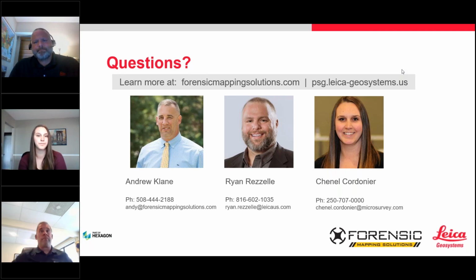Okay, great. We have a question here about the ground sampling distance. Andy, would you say that 1 centimeter is the go-to sampling distance to use? Right, so what Pix4D recommends is trying to process to a range of 1 to 3 centimeters for your ground sampling distance.